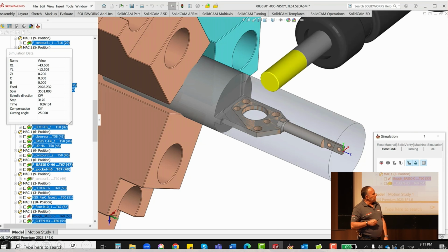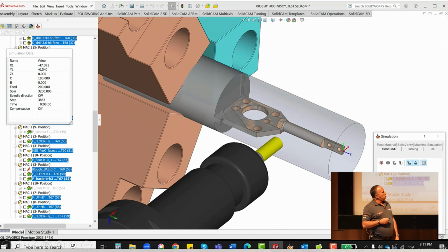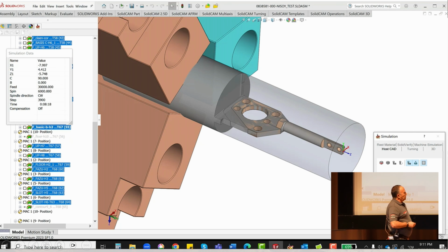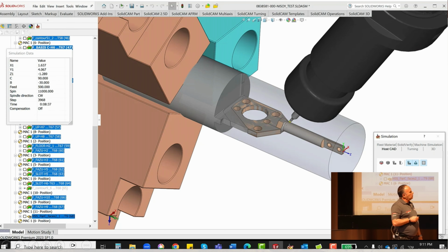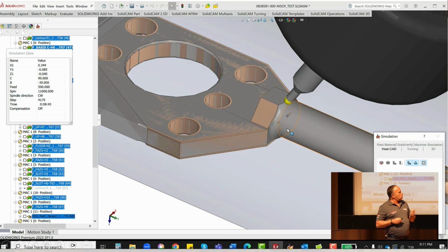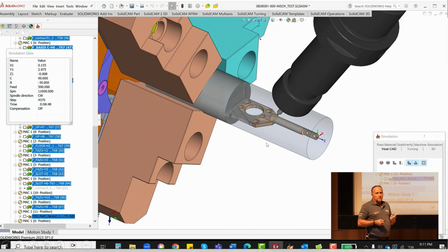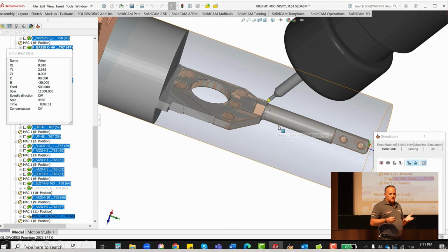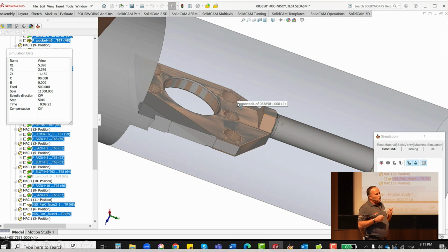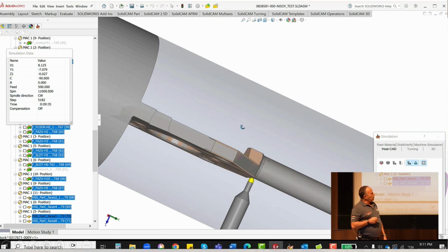And after we finish with this, we will complete now all the finishing operations. As you can see, it's very fast. You can see chamfering, profile, drilling. As you can see here, now we work with HSS, for example. HSS is something basic today in our system. When I sell 2.5D, HSS is inside. It is one of the packages because it's so easy to define and very powerful to machine surfaces. We can see another operation like chamfering here.